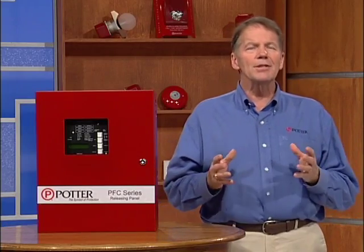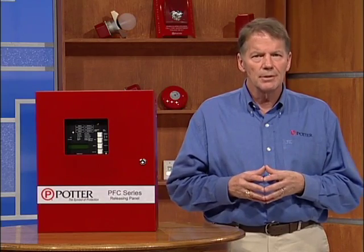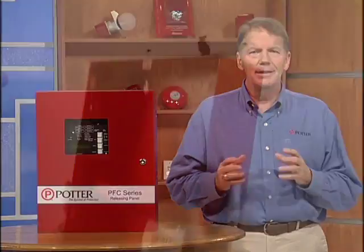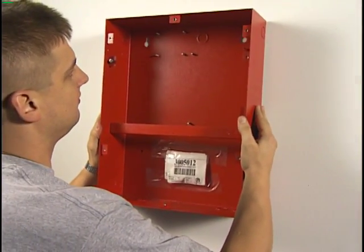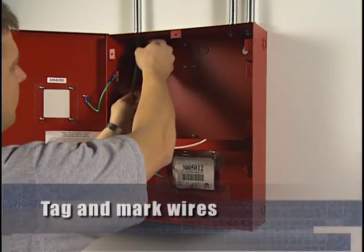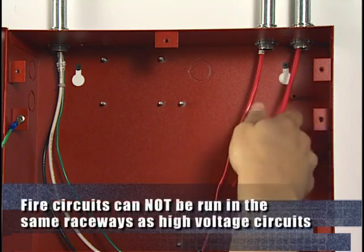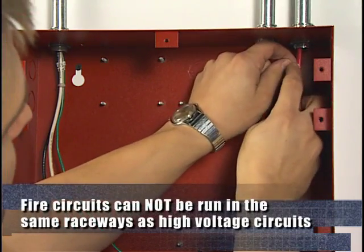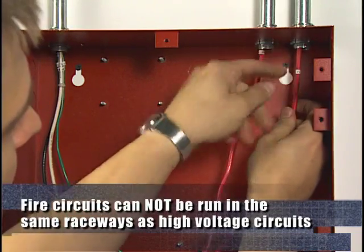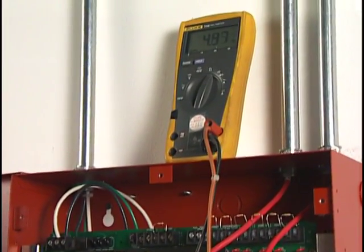Now, you are ready to install the panel. Select a location that's easily accessible. Then carefully remove the panel and any modules from the cabinet. Next, mount the cabinet, complete all conduit connections, pulling all system wiring throughout the conduit, and tag and mark the wires. It's important to remember that fire circuits cannot be run in the same raceway, cable, or conduit as high voltage circuits. Now, install the panel and any associated modules in the cabinet.